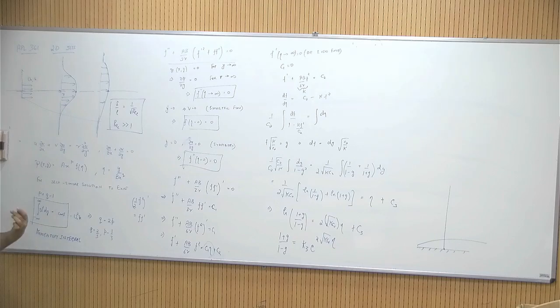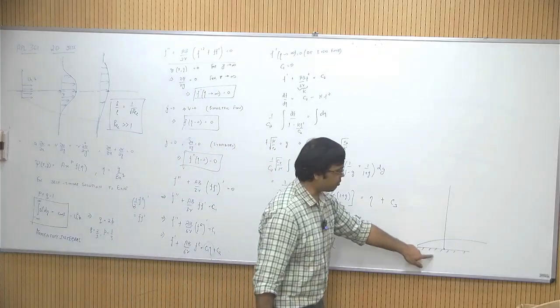It is the rate of transport of that momentum that is constant. It's very difficult to imagine this quantity, honestly speaking. You might as well imagine it like half u square dy, so kinetic energy in x direction is constant, you might as well think of it like that. So it is the minus infinity to infinity integrated quantity that is constant. You can derive a momentum integral equation for boundary layers as well.